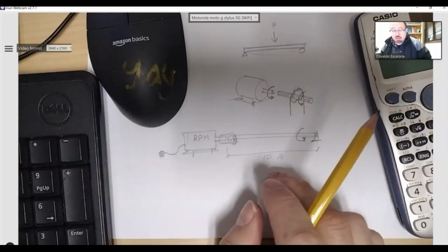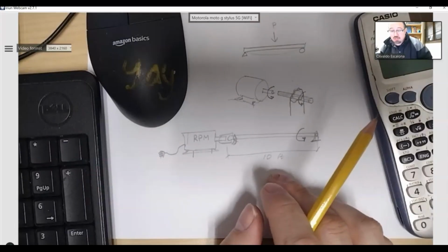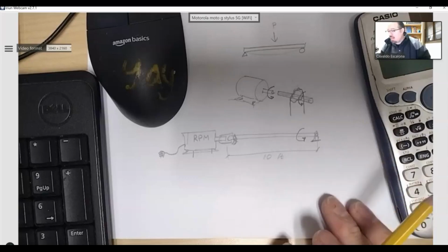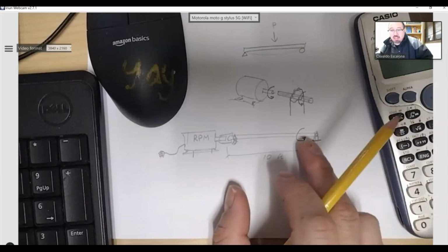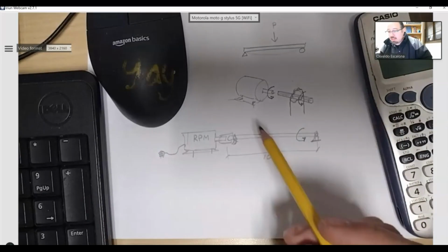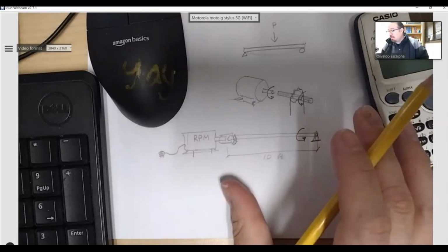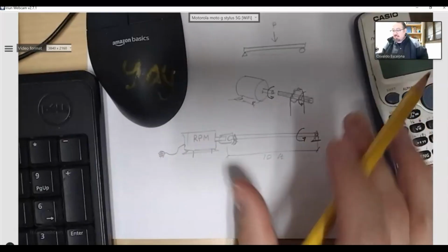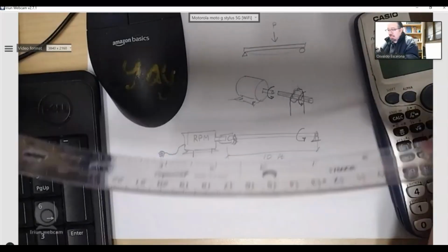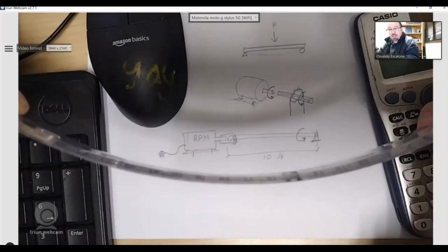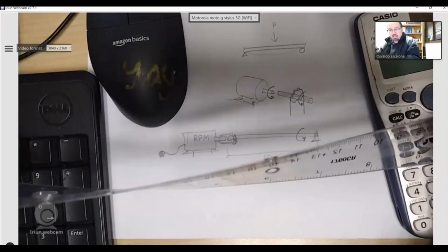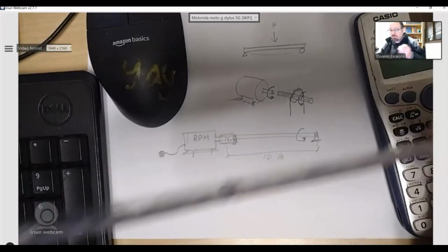Let's call it torsional stresses and shear stresses due to the torsion. Okay? And shafts are designed to take torsion. So you design all of these shafts because they're going to be carrying a gear somewhere in the middle, but they're usually not designed to have bending. What is bending? This is bending, right? This twistiness is torsion.